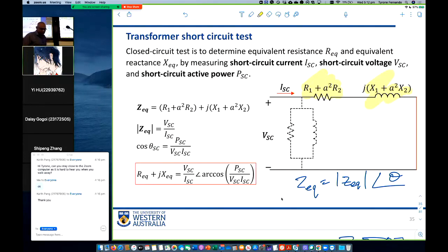So here, we have the ratio of the voltage to current, and that's going to be the magnitude of Z, because I'm going to think of this as Z, right? Magnitude of Z. Yeah? And then, if I take the ratio of the voltage to current, and the angle, right, VI cos theta is power, so we can calculate the theta, and that theta is just the Z angle, right?